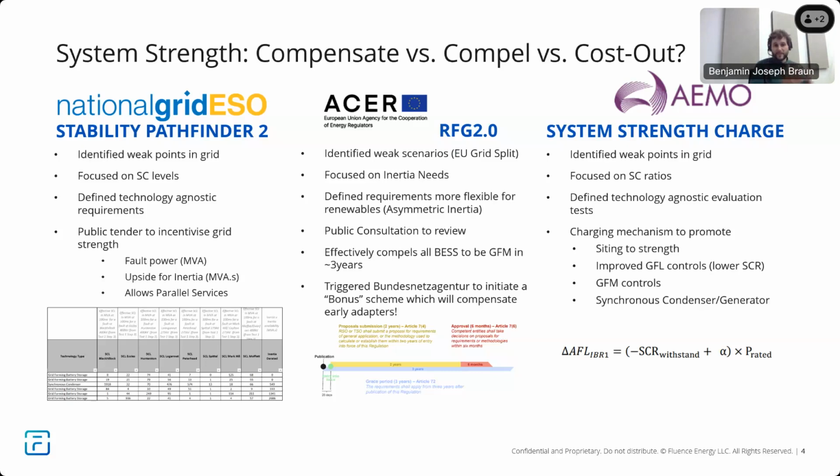We know that grid forming technology has gotten to a fairly mature state, and they themselves also released a grid code defining how to quantify that grid forming capability. So they said, right, if you're a battery, you're grid forming, you can help strengthen our grid. You can also design your plant to participate in other services: energy arbitrage, frequency response, voltage response. Those are all open for you. And from that, tell us what it would cost, and we'll see whether we sign up for a contract with you or not.